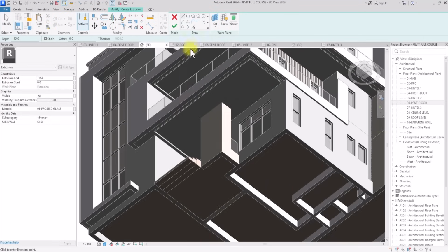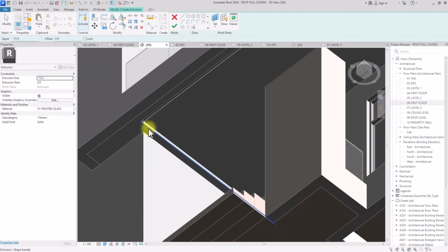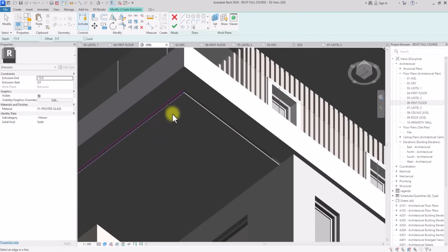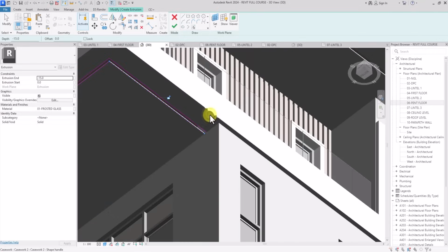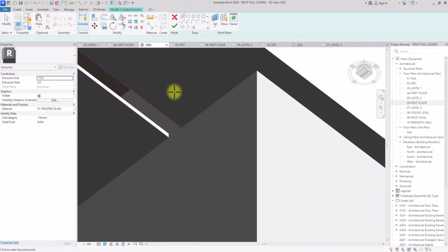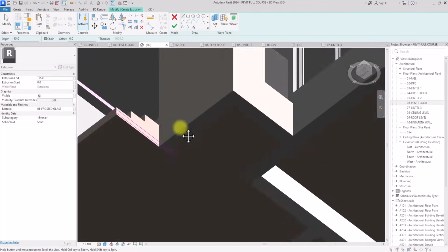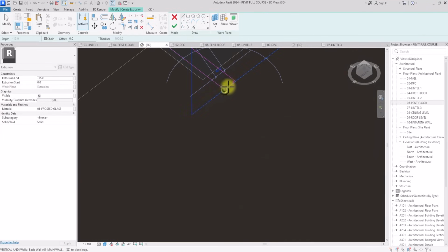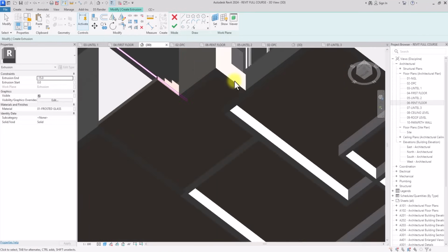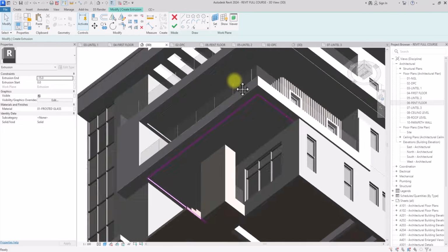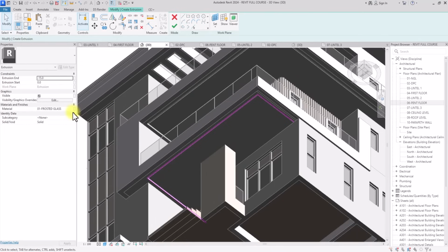So under this ceiling, I'm just going to click the pick line tool, and I'm going to mark out the spacing I made for the luminous material or the LED light. For this LED light, I'm just going to make a simple extrusion, but I'm going to apply a separate material, and I'm going to name the material luminous material. So when I'm using it in a rendering software, I'll be easily able to change the nature of the material to make it luminous.